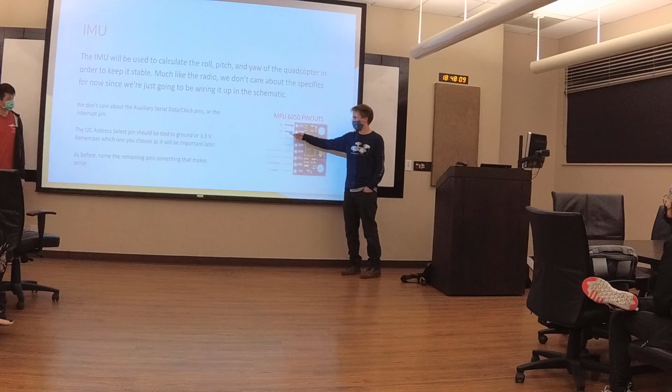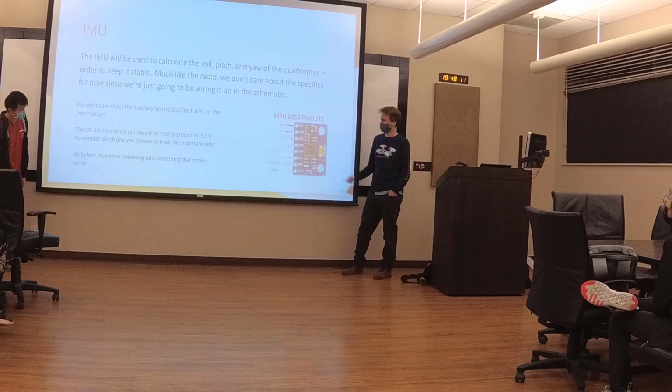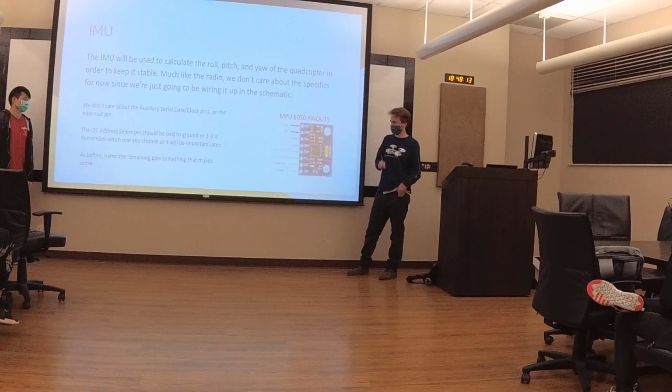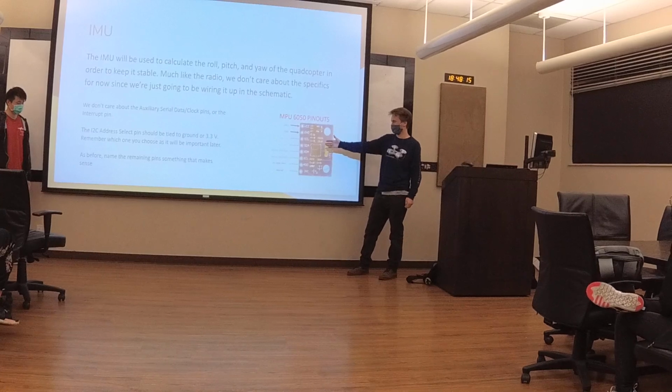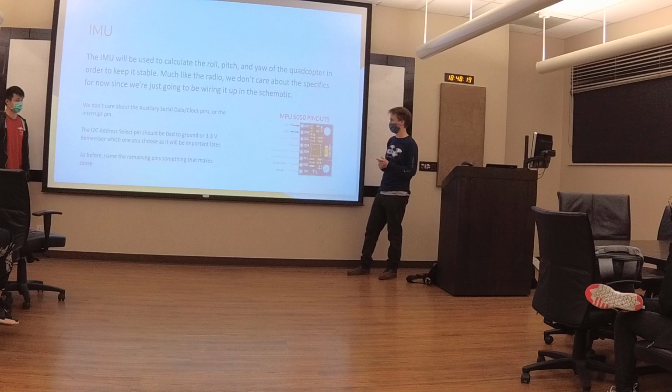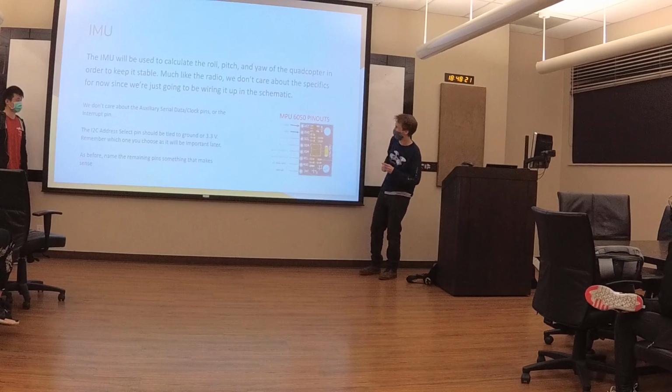We won't be worried about these, but what we are going to ask you to do is just add labels to these. That being said, we're also going to have a request for you to put a couple of decoupling capacitors in front of these. And that's going to be part of the lab where we specify which values we want at which pins.